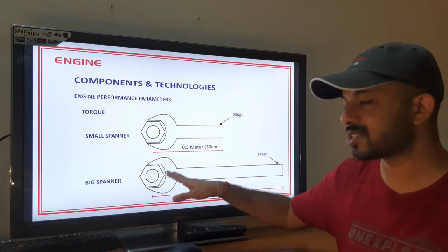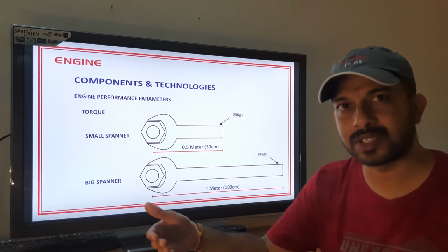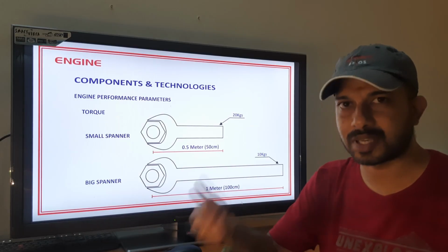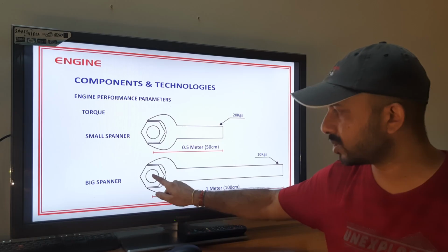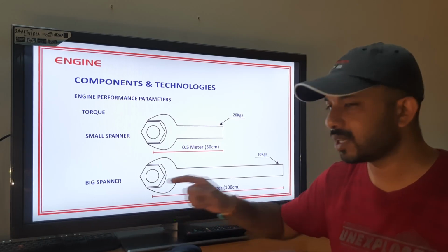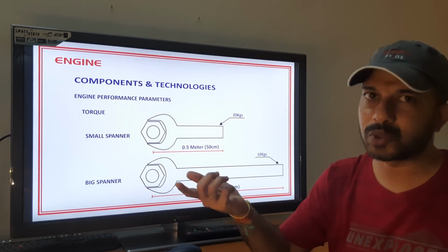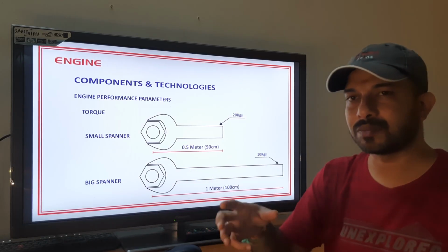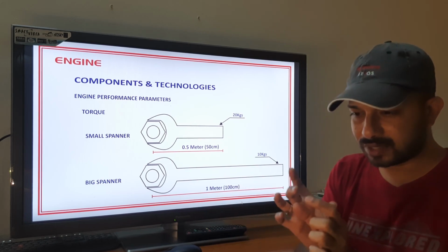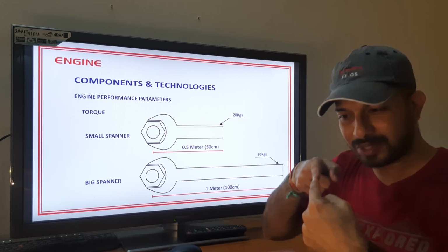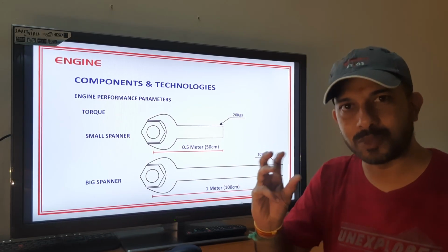What is mentioned as the torque in the service manual or the manufacturing instruction manual should be the same as that. You would have seen some marks there, from the bolt to the nut to the body, in many cars. If you see yellow, green, or blue colors, that makes sure that's the torque and it is marked there. If the nut is loosened, those line marks will show variation, which means those nuts or bolts are loosened.